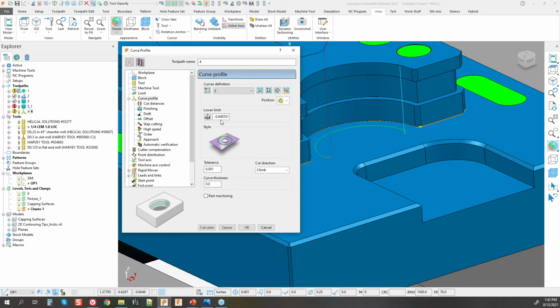The other reason for this is that we can go lower based off of the depth absolute versus trying to manipulate the block to create that depth distance. That's a big thing with these curve profile machining versus our 3D. 3D is automatically doing it per the surfaces. Our 2D gives you that selection and gives you that choice.